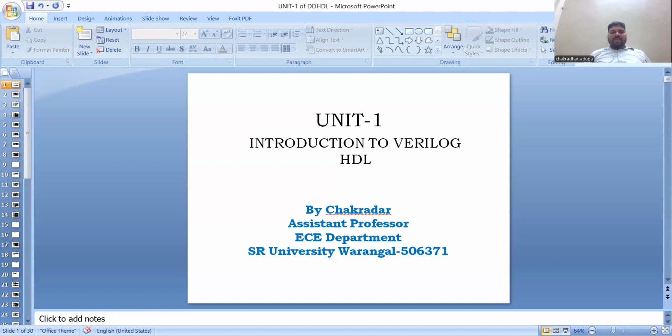An optional signed specifier 's' can be added for signed arithmetic. For example, -8'd3. It's an 8-bit negative number stored as the 2's complement of 3. Second example, -8'sd3. It's used for performing signed integer math. 4'd-2 is an illegal specification. You cannot mention the minus symbol between the base format and the number; the minus should come first.